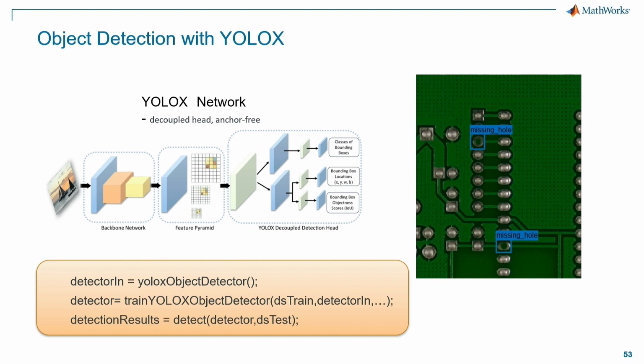So YOLO is the framework of deep learning, equipped with some recent advanced detection techniques like the decoupled head, anchor-free, and advanced label assigning strategy. YOLOX achieves a better trade-off between speed and accuracy. So then you can get your model much faster. Using this model, we see those missing soldering pads from this image.